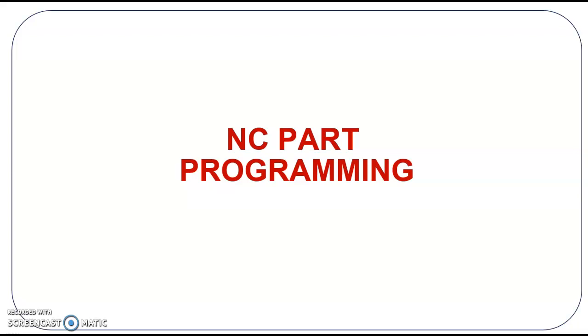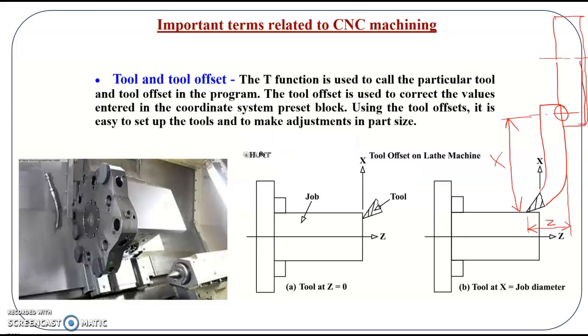Welcome to the third video on NC part programming. In this video, we are discussing tool and tool offset with reference to a CNC lathe. In a CNC lathe, the common method of fixing the tool is on a hexagonal turret.